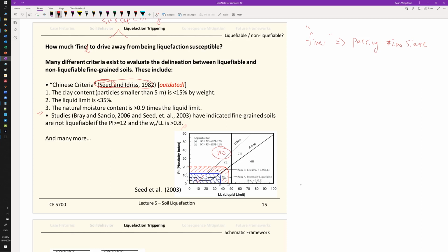But when you clearly have sand layers submerged in the water table, or silt layers, or any of the blue and red fine materials shown in this chart, underneath the water table, then your soil is susceptible to soil liquefaction, especially in California, where the area is seismically active.